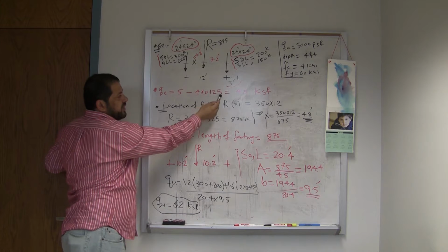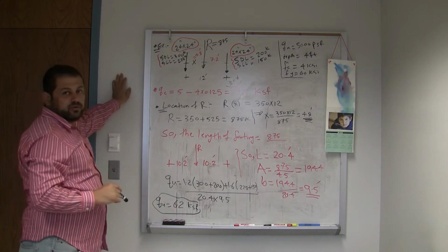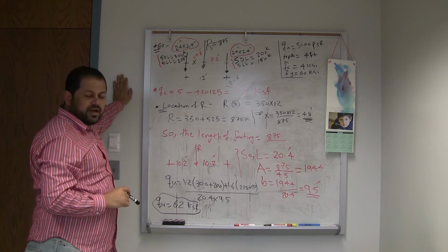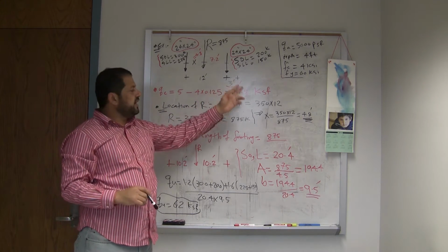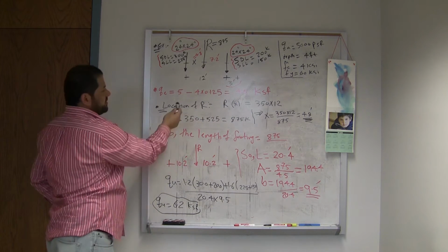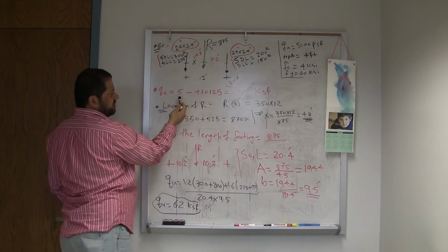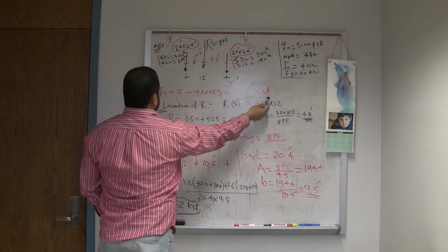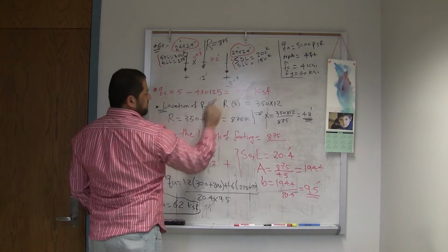So we always assume a weighted average between those of 0.125 kip per cubic foot, or 125 pounds per cubic foot, which is 150 for the concrete and 100 for the soil. So if I subtract 4 times 0.125 from 5, the remaining Q effective for carrying the load from the two columns is 4.5 KSF.